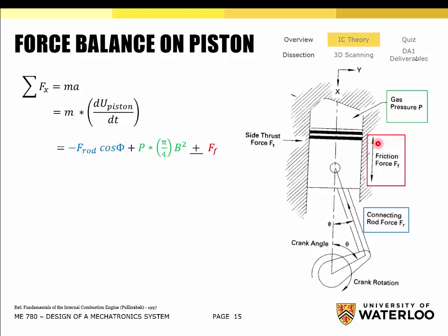Side, not both sides. Think about it like this. When you're pushing up on the cylinder, it's going to wear out one side. But when you're pushing up, you're not really resisting the combustion forces. You're just pushing against the cylinder pressure. When it's getting pushed down on, it's going to have a lot more combustion pressure, which means a lot more side loading on the piston. So in one direction, it's going to be more than the other. But it does have a horizontal component regardless of the direction, because of this angle theta.